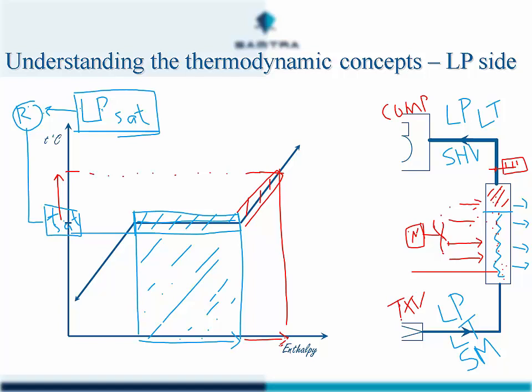Okay, so the main way that we are shifting heat energy in a refrigeration system is by means of latent heat energy transfer. Having a superheat value after the evaporator is good because it means that we are maximizing the refrigeration effect across our evaporator, but at the same time we're protecting our little compressor from trying to compress an incompressible liquid.